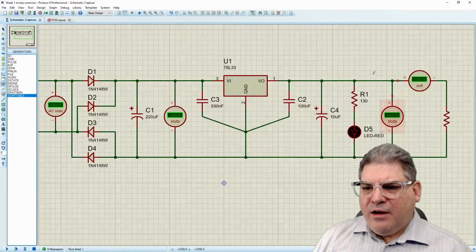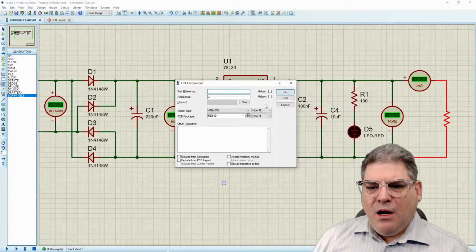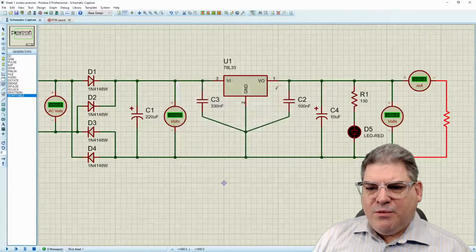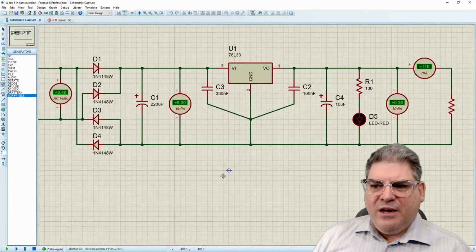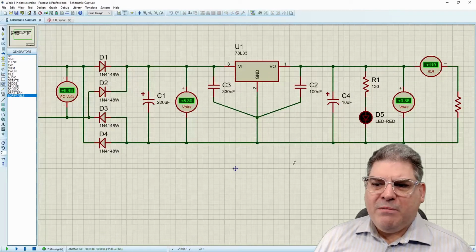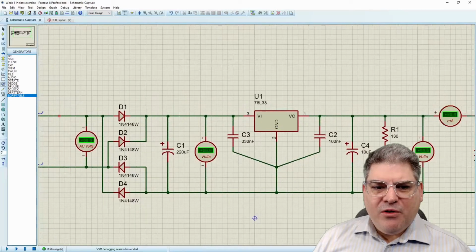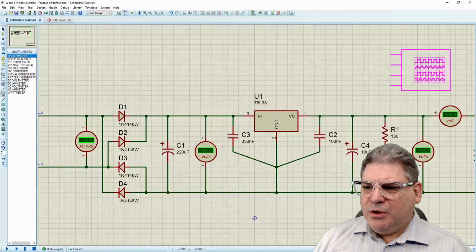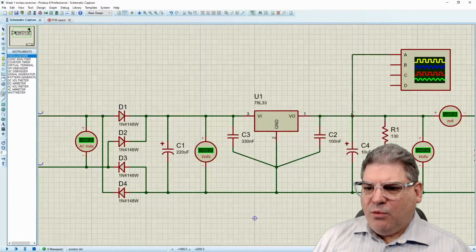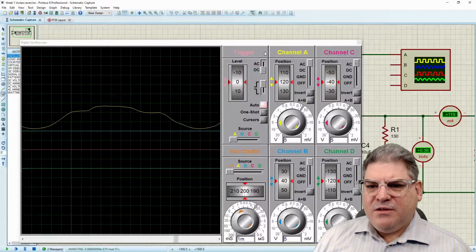Okay. And so here we are. I've changed this out to a 3 ohm resistor, and it should be 3.3, but it doesn't really matter. When we try to run this, you'll notice that I don't get to my 250 milliamps, and my voltage has dropped substantially. And so what's going on here? Let me throw in an oscilloscope here super quick, and we'll just take a look at what's going on with that point.